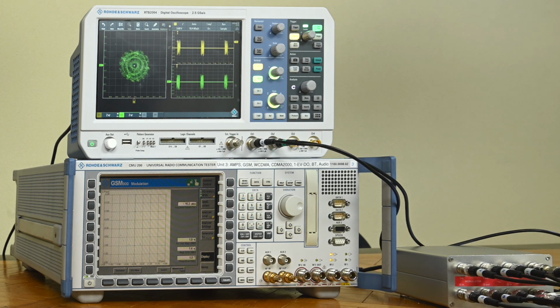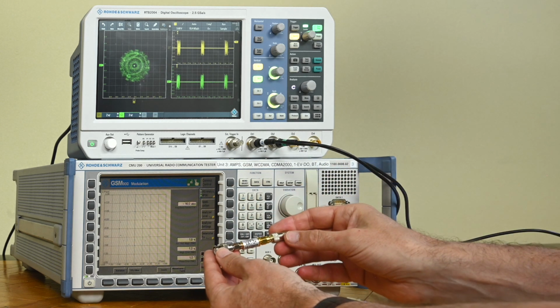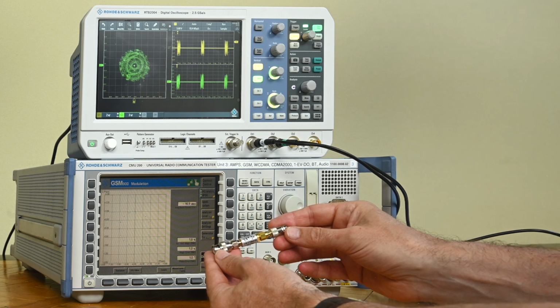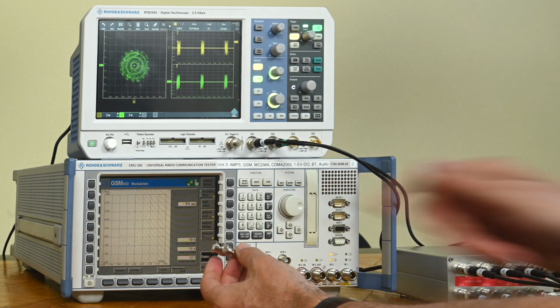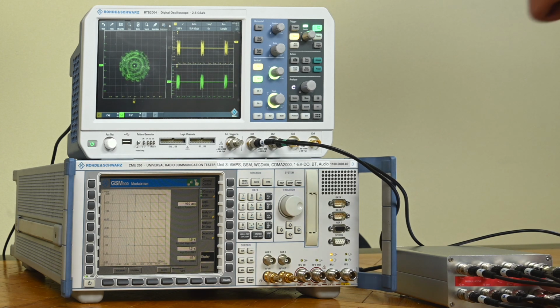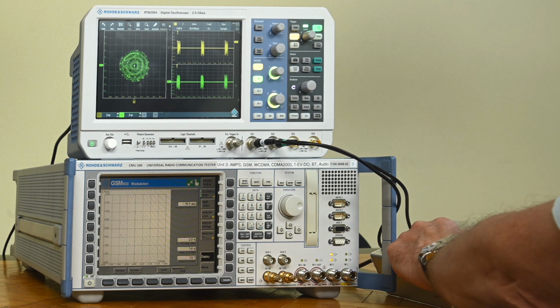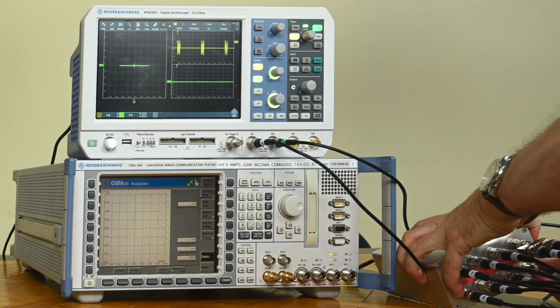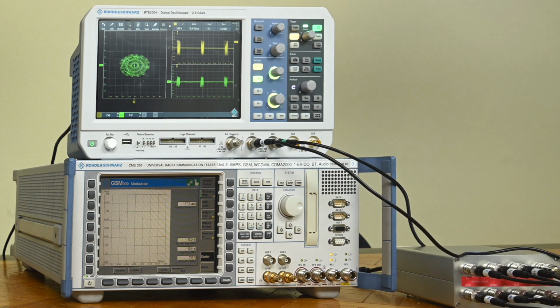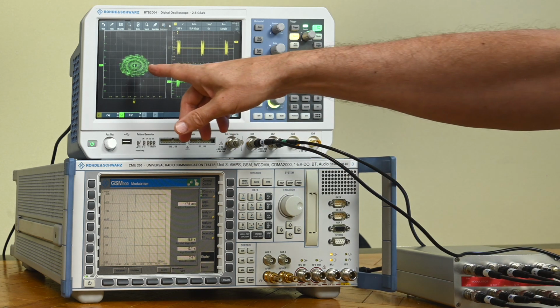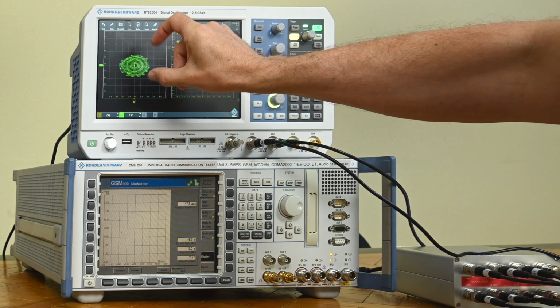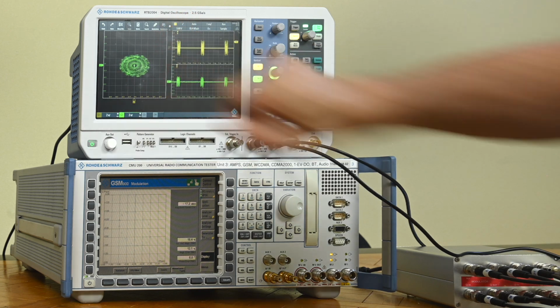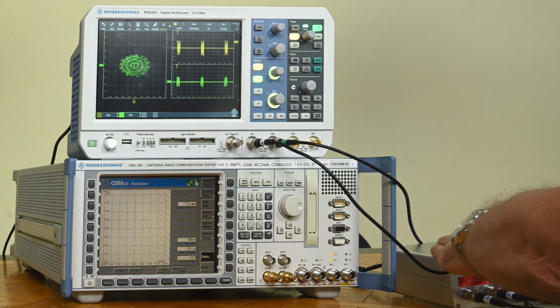Another thing I could do is try to see what happens if we attenuate some of these signals. For this I'll just use a small attenuator, a 3 dB 50 ohm attenuator, and I'm going to put it in the receive Q channel and see what happens. Let me pull it out. Put it back in again. Okay, we get something a bit weird. This signal actually has become half the magnitude on one of the two scales, the Q scale.